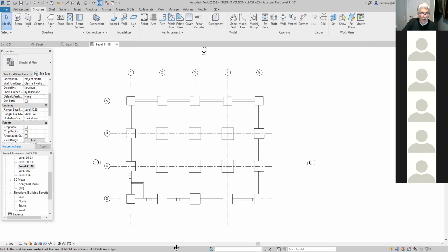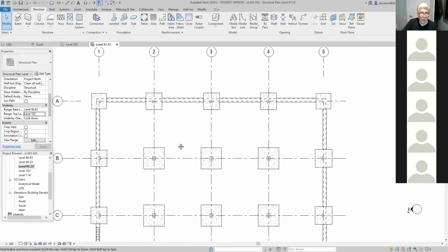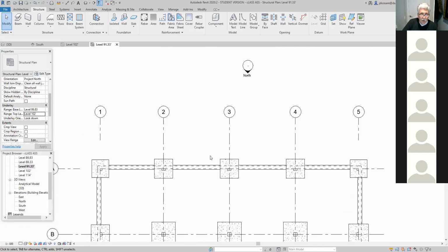Okay, so now that wall is in, let's go back here. Now, I don't want to do this now. You should first put your opening in here, and then come in here and put in the wall. Because if you put in the wall, you won't be able to use the north elevation to put the opening in. So let's go to the north wall, we'll do that at the very end.